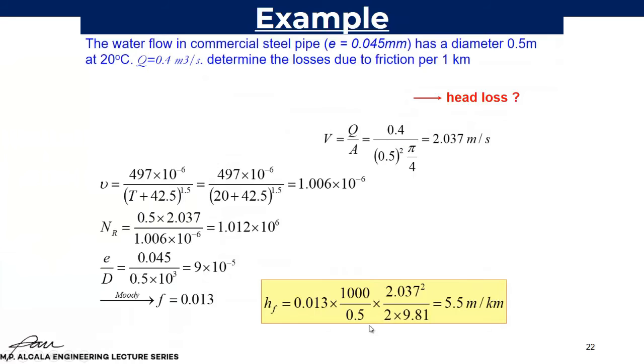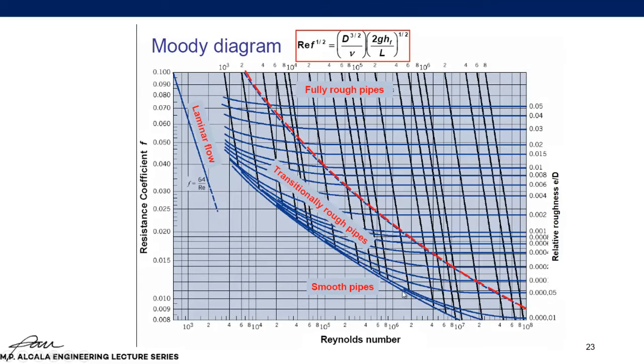Okay, so I have arranged this, class. Sorry about that commercial break. So 1 times 10 to the 6, that is your Reynolds number, okay? So for your relative roughness, 9 times 10 to the negative 5. So, looking further at our Moody diagram, 9 times 10 to the negative 5 is simply here. And your Reynolds number is about 1 times 10 to the 6, okay?